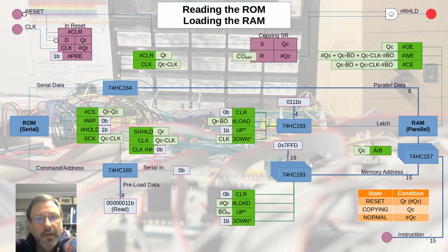Okay, well, I feel reasonably comfortable with this design. There are going to be some challenges with it. I am not totally certain that the shifting in and out with the Serial EEPROM and the shift registers, if the timing of that is going to work out properly. I'm going to have to pay really close attention to that. Also, I have to pay close attention to the counters. The reset at certain points, I've got to make sure that those intervals are accurate and I actually get the correct number of counts associated with them.